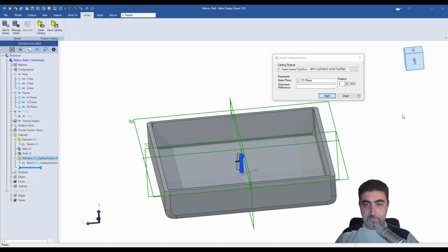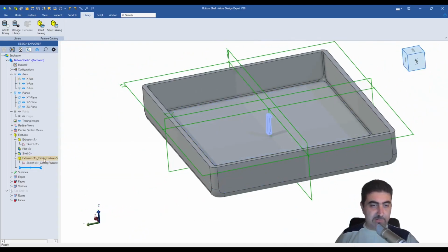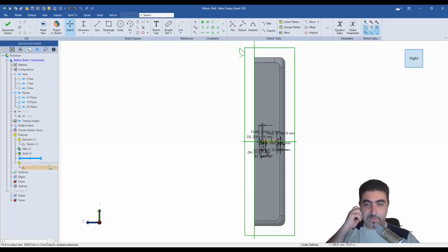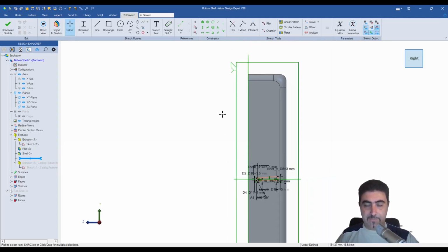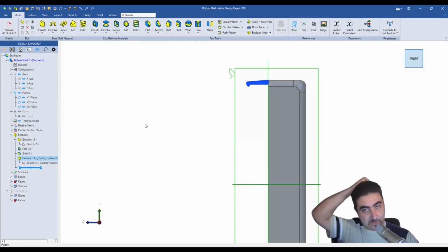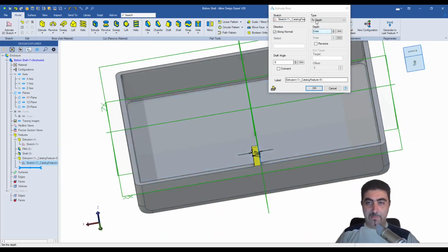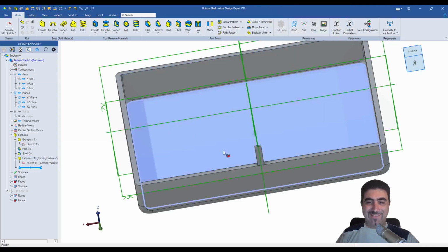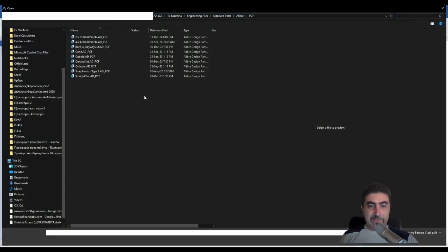So this one, I'll just hit apply. Now my snap hook kind of hovers in there somewhere. I need to go into my sketch and tell it where I want it to be, right? So where I want it to be is here. I'll just imprint here, this area, using my trick, and I'll just say this point and these points are coincident. You know what I can even do? Make this into a midplane. Right, there you go. And now I'll just add it again over here.